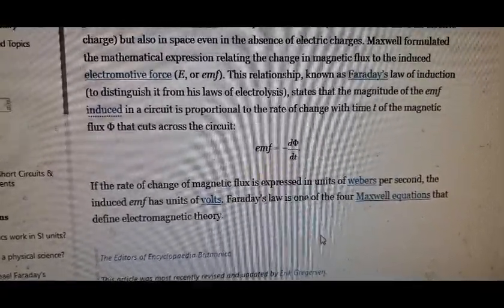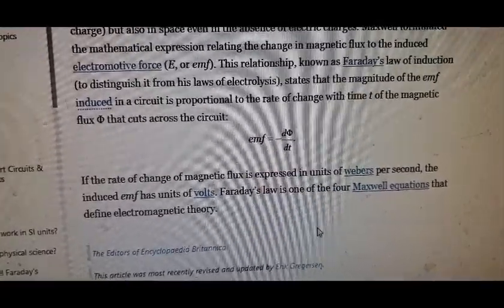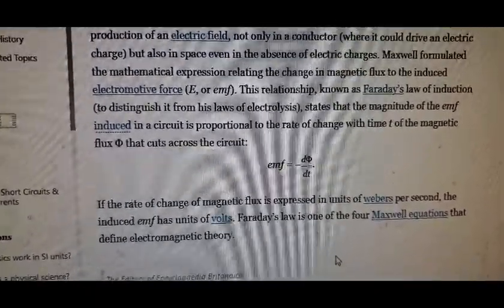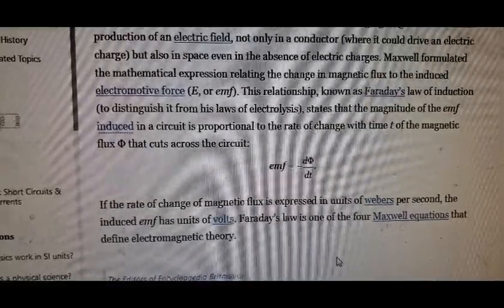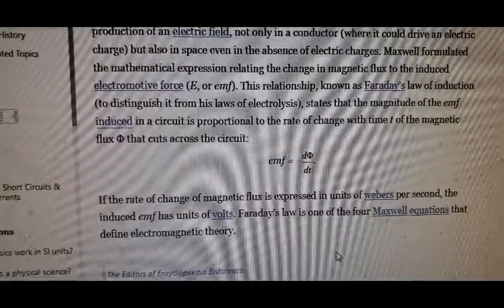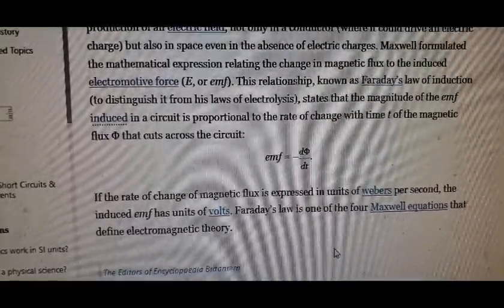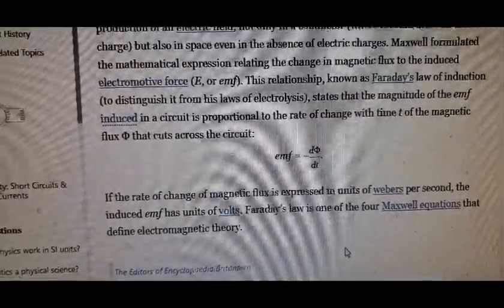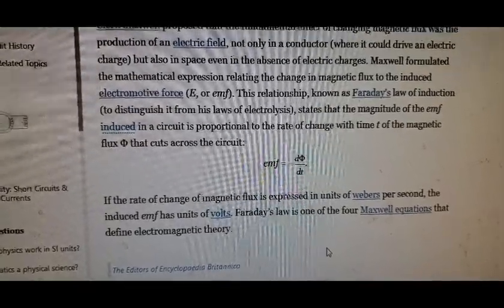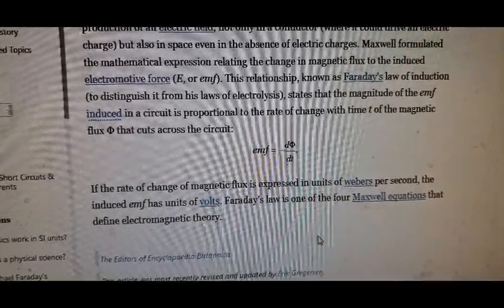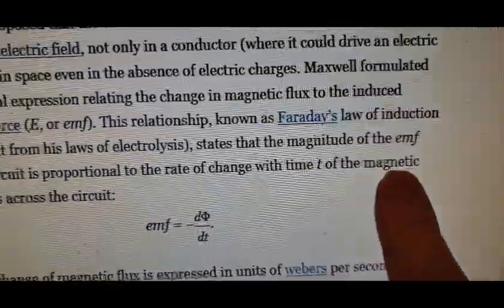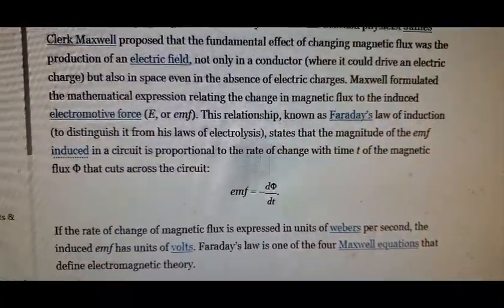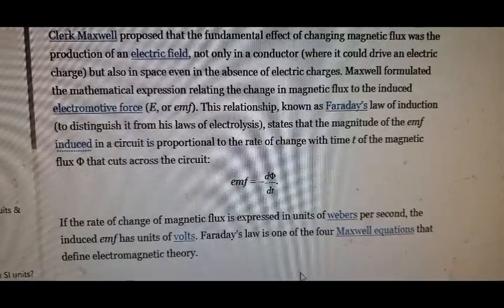Or if you put 200 turns of wire on a coil, but you now increase the wire diameter such that those 200 turns also would allow 1 amp through at 10 volts, then now you've doubled the strength of the electromagnet, but you're still drawing 1 amp of current at 10 volts. So again, the strength of the magnetic field, which will determine the change of the magnetic flux, is also not directly proportional to the input energy.